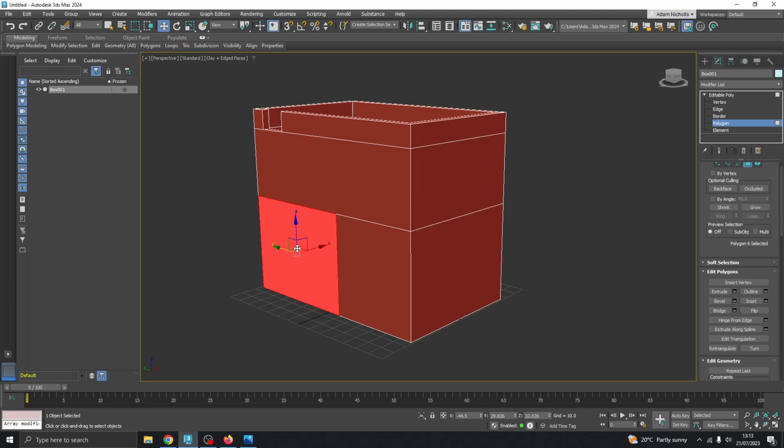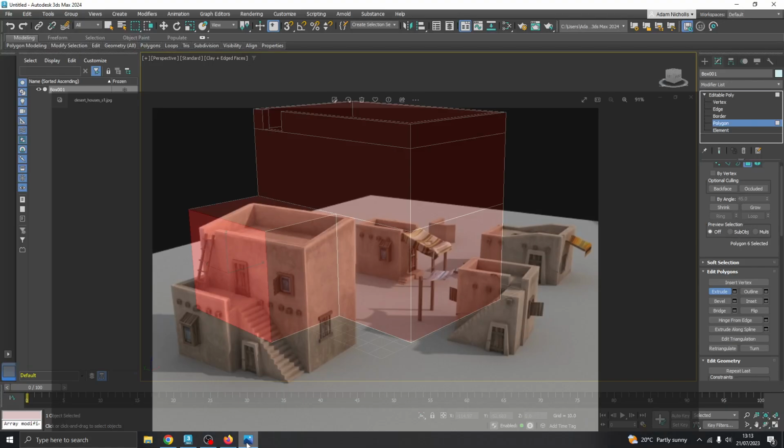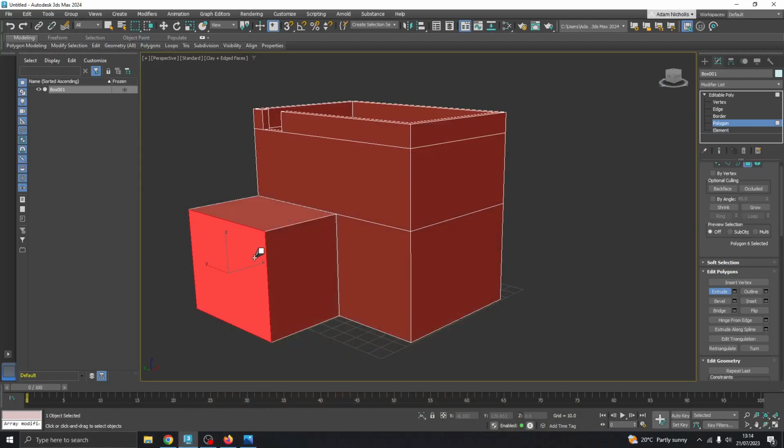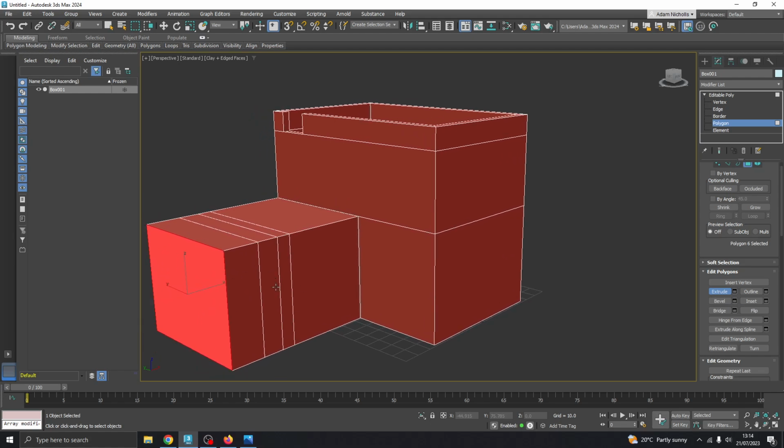Again, it's that process of drawing in those edges until you have a polygon the right size in the right place that you need to use your other tools to progress on. So this time now I need to go extrude, and I can extrude this out. Okay. Again, if you've gone too far or not far enough, don't start doing this until you've got far enough, because it adds all this extra lines and geometry that's just going to mess things up.